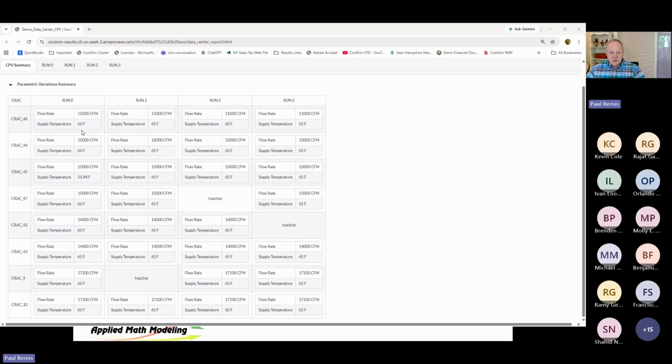So the way to do that is to go out and measure. If it's an existing data center, you can take some measurements on supplier temp and just set the supplier temp. The equipment itself will have its own CFM. So you'll be able to look up the max CFM of the equipment. The cooling unit generally will tell you what its CFM is, either on the front panel or through a specification. If you know the CFM and you know the supplier temp, you've pretty much dialed that guy in. He's in. Same for the others.